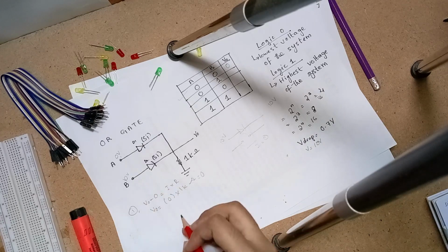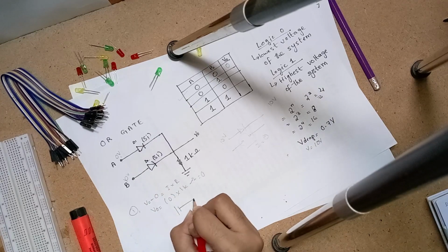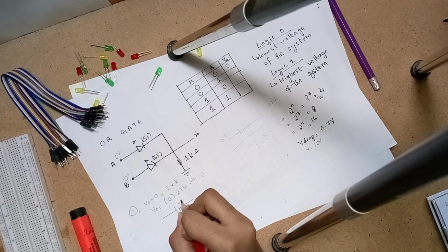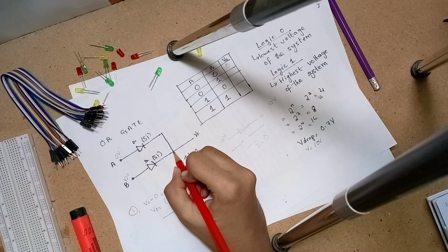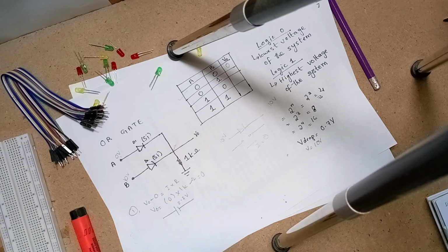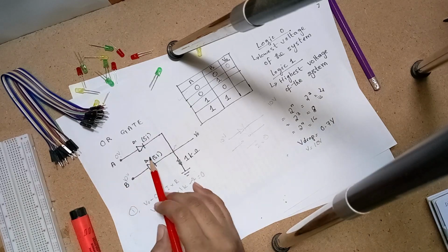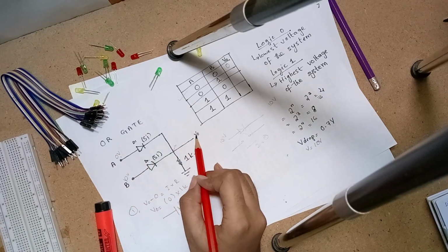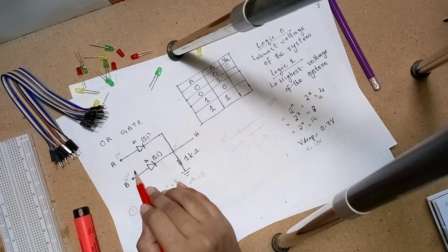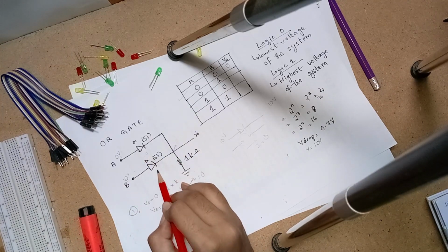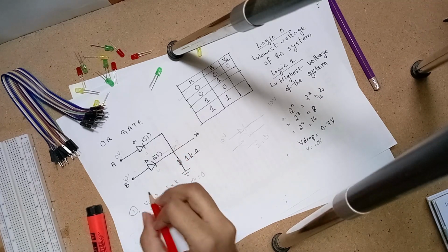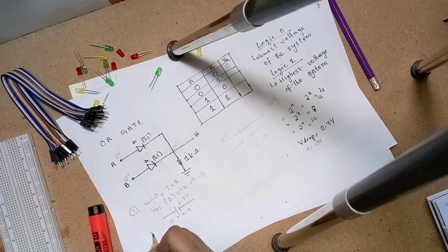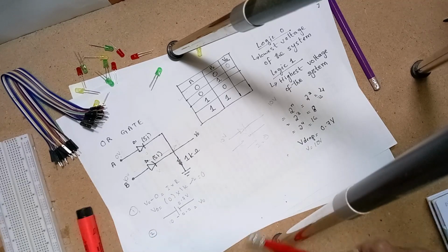Now in this case, we are going to replace it with a voltage drop like this, and we're going to write 0.7 drop here. So now how do you solve this? We have to find out the output voltage at this point, V naught, and what we are going to do is subtract the drop from the supply voltage, which is directly connected with the output voltage. So if 10 volts are being applied and 0.7 gets dropped, what is the output voltage? We are just going to subtract the 0.7 drop from the 10 volts, and it gives V naught.